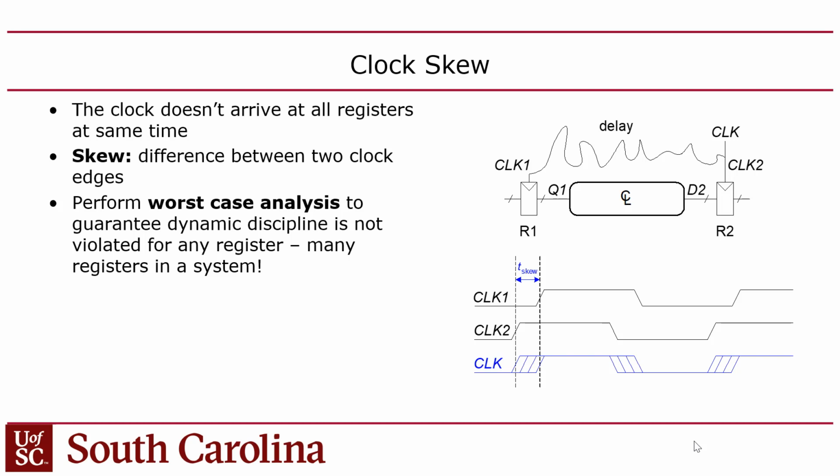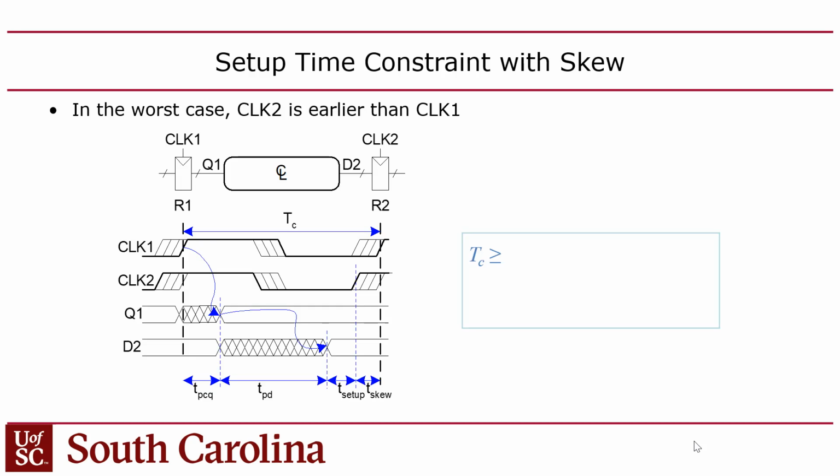Well, because what might happen is, for the propagation delay, if you have two registers, R1 and R2, and say R1's clock is running late relative to R2's clock. In other words, R1's rising edge comes after R2's rising edge. R1's clock is phase shifted to the right.